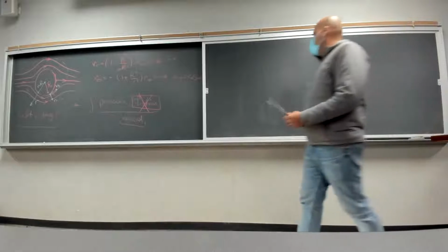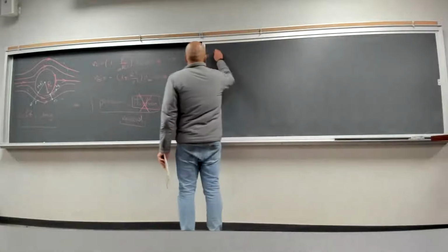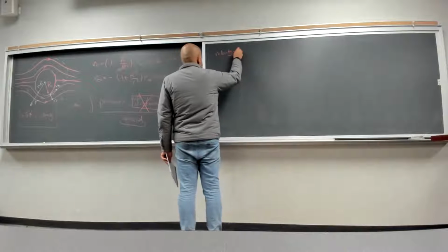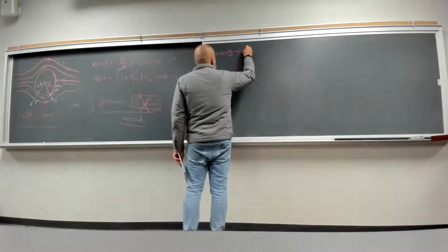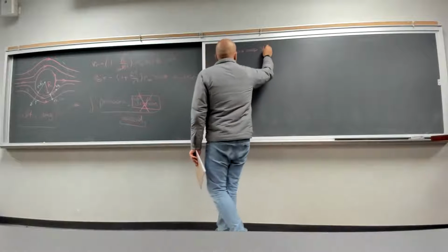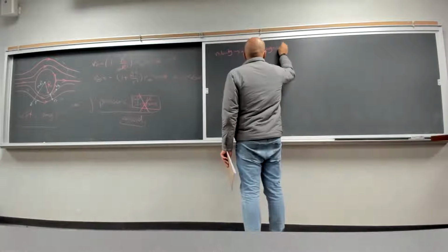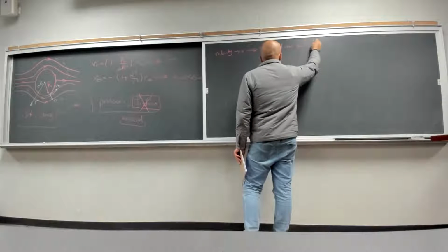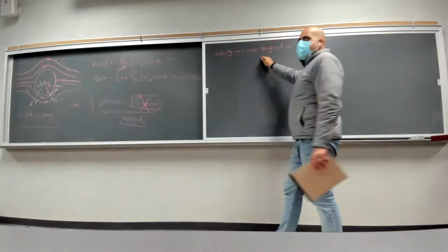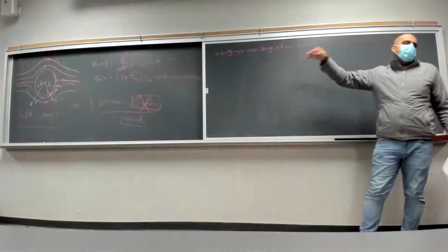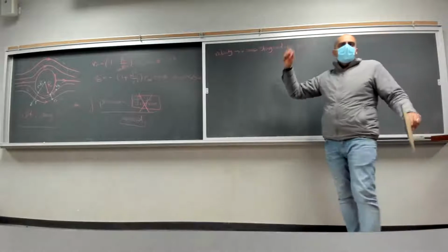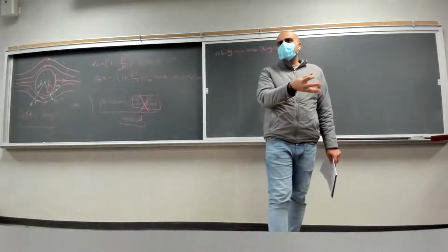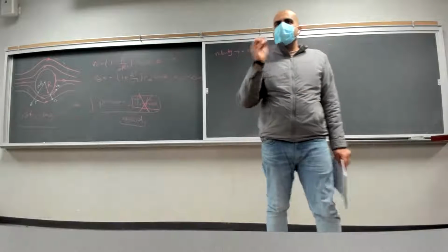Velocity is 0. These are the points where the velocity is going to be 0. So velocity is 0 at any point. Those points are called stagnation points, which is in line with the definition of stagnation pressure or stagnation properties. The idea was we bring down the velocity to 0 and measure pressure. That pressure is going to be your stagnation pressure.